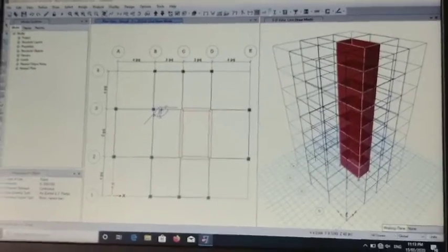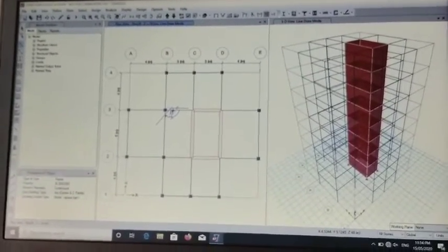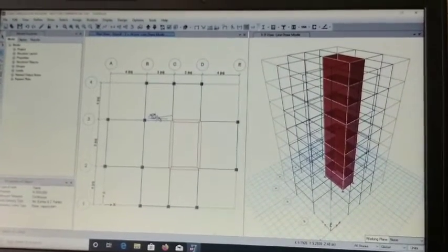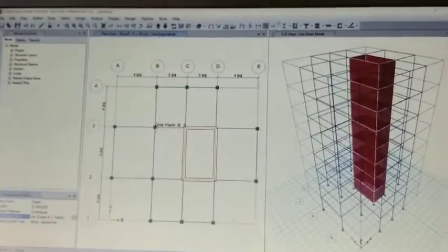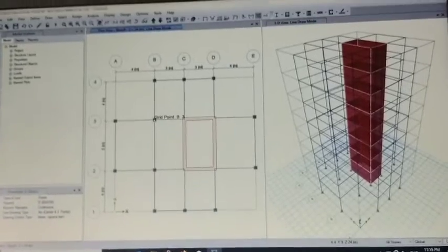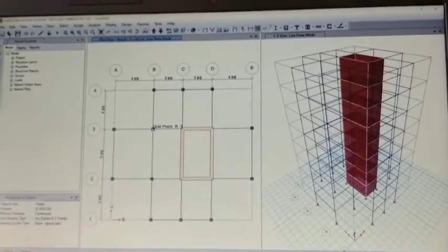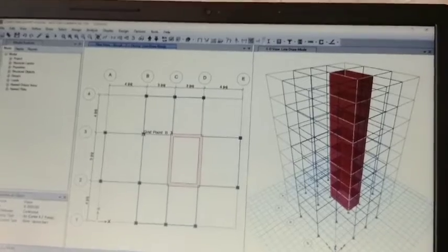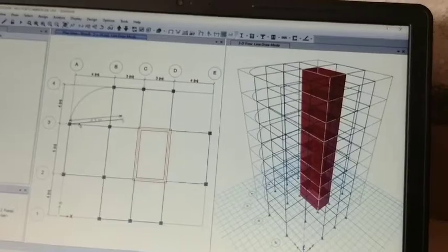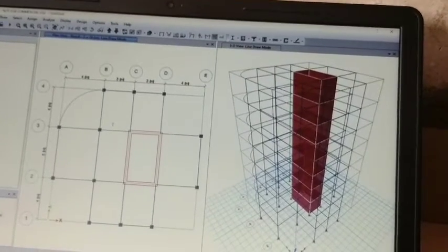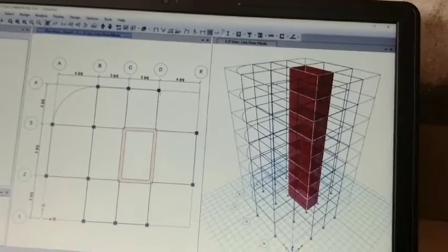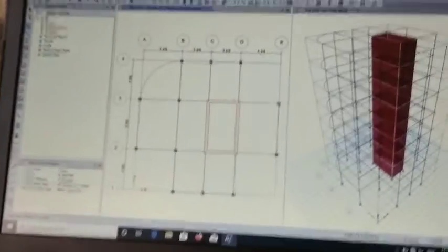After selecting arc center and 2 points, click once on the center of the arc. Click on the starting point of the arc, click on the end point of the arc, and right click. Follow the same procedure for drawing another curve arc.